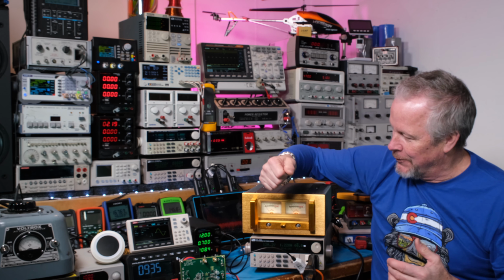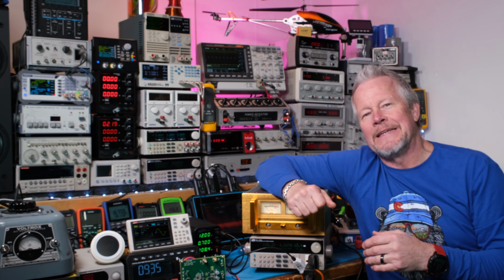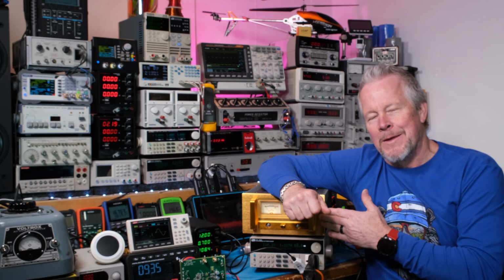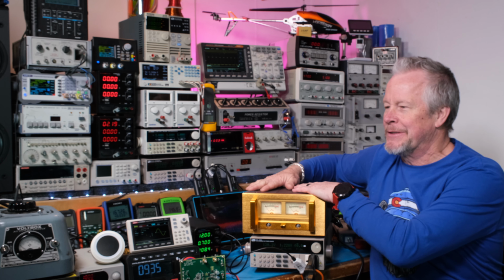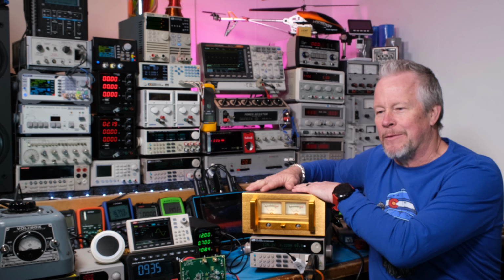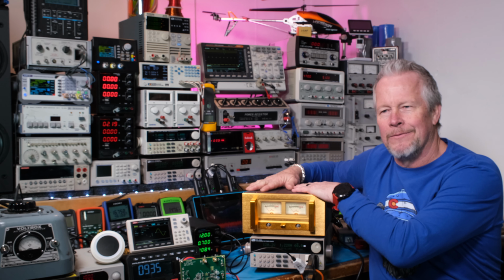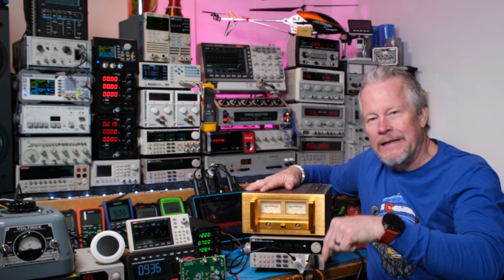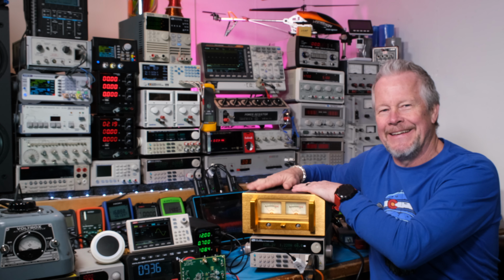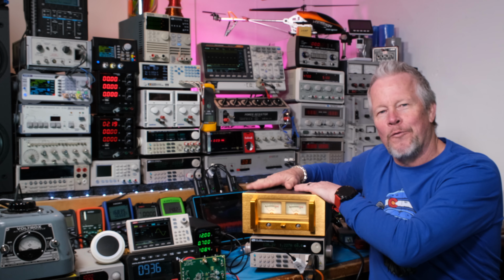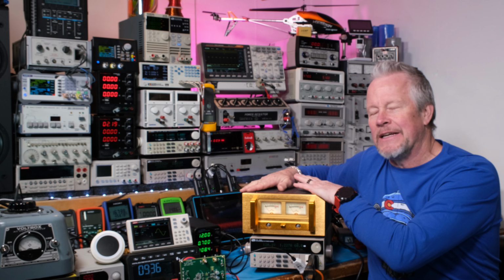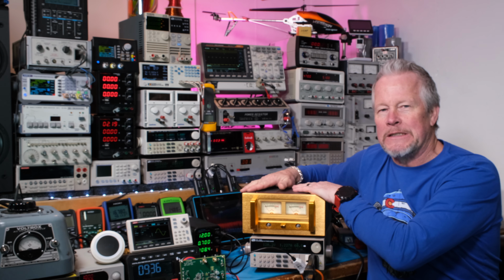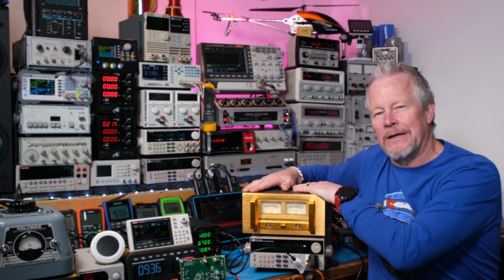Hope this was helpful, useful, and that you could see that just because you have big toroid, big capacitors, big everything, big transformer, there's nothing linear about that. You can see there's no linear waveforms. It's a low frequency switcher. After that, it should be regulated. And then you could say it's a low frequency switcher. Second stage is linear regulation.